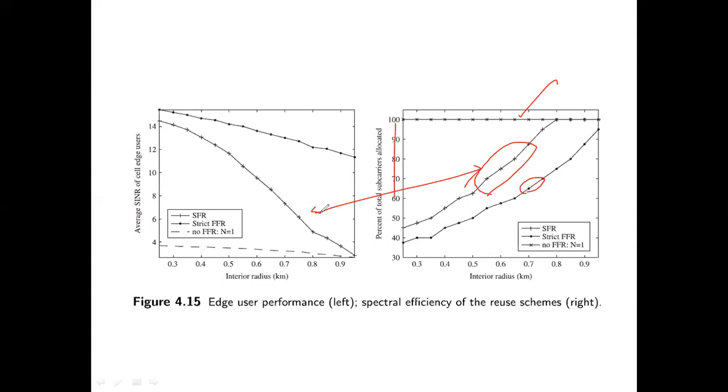So two things we saw, right? One was the clever power allocation: the farther away the mobile phone, whatever it is, the more power you allocate so that the SNR is better. The closer it is, the lesser power. That was one approach. And the second one is frequencies, how they are allocated.